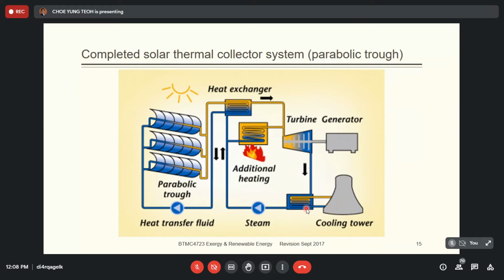Okay, so once it's cooled down, the steam is now very hot, so it's expanding. It's already expanded. So to create the pressure again, first I need to reduce the pressure, by condensing it back into water using the cooling tower. Okay, and then pump it back into the system, so that it can create the pressure again and again. The pressure will be created only when you change the phase from liquid to gas. Okay, so you cannot say the steam is still hot, so I pump the steam into the heat exchanger again to heat it up. Not that case, because it cannot create enough pressure already.